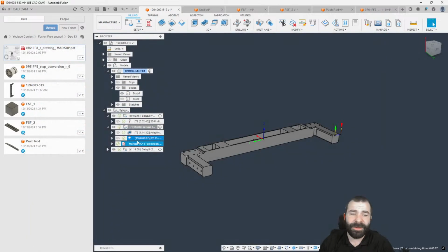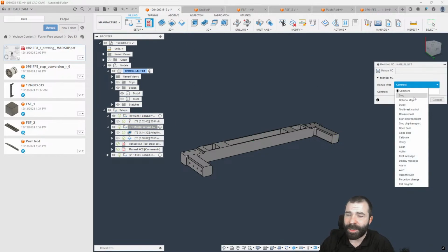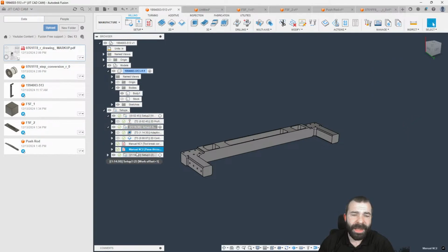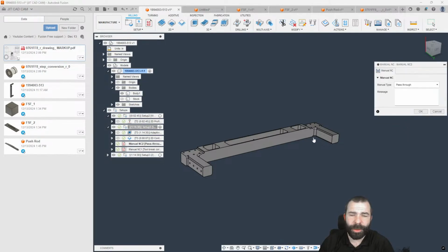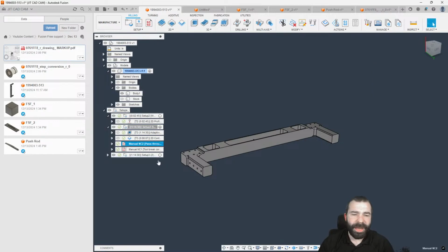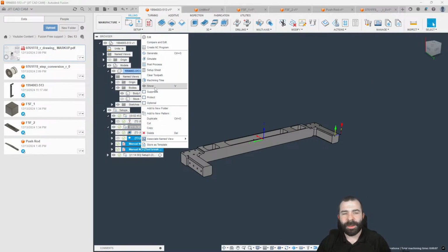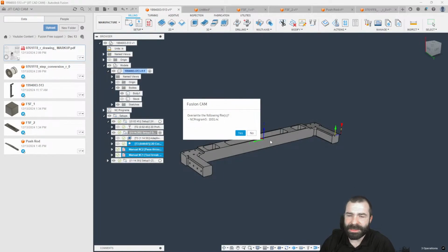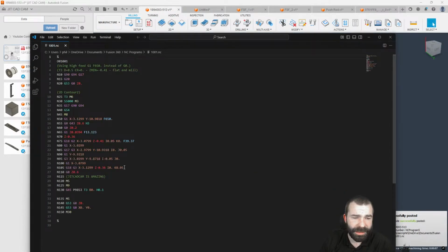And if you guys have never seen me do this one, we could obviously go in. You could do a pass through, which a lot of my customers do. That pass through is basically whatever you put in the pass through. We could say something like "jitcadcam is amazing." And what that is going to do is when we post out, it will actually insert that automatically into your G code as well. Now the problem is, notice how my pass through is getting called before my M5 and M9.